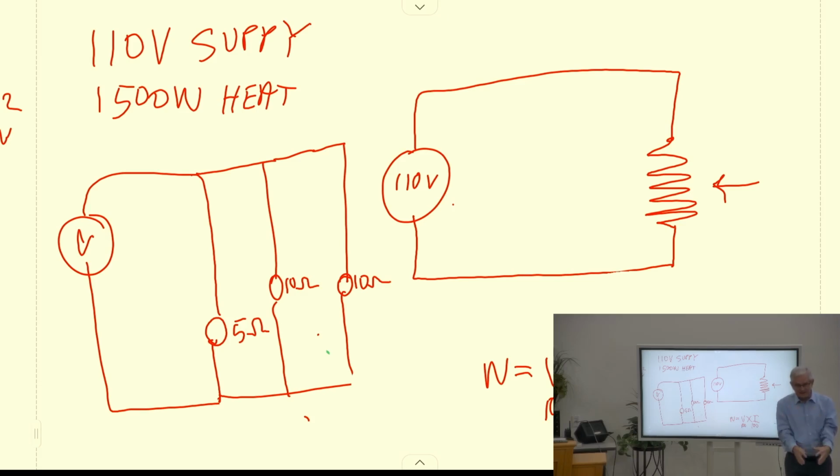So my generator wants to be at a lower voltage. But as soon as I get that power out of my generator and I want to send it 100 miles, if I can transform it up to 10,000 volts instead of 100 volts, now I use a tiny transmission line. So that's why transformers took over the world: because of the transmission problem.